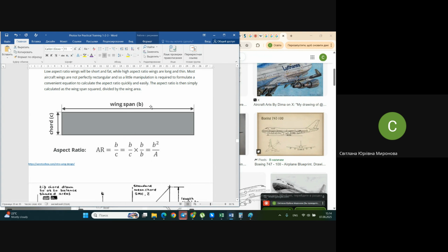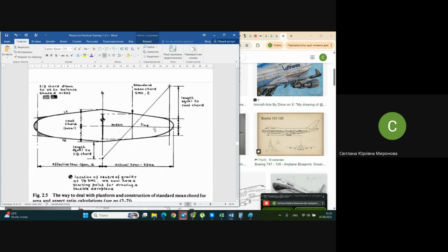In case it's a swept wing, you need to go into additional constructions, let's say, and to work with the so-called mean chord. The value that you may take from span and wing aspect ratio, for a swept wing, will be the so-called mean chord, somewhere not even in the middle of the wing.